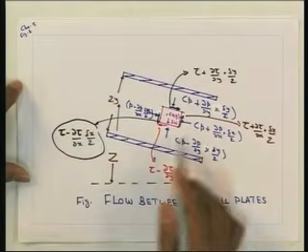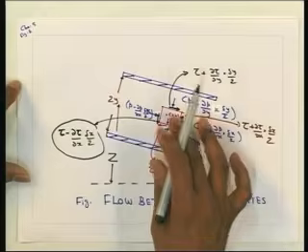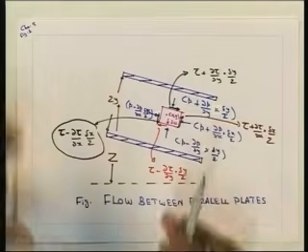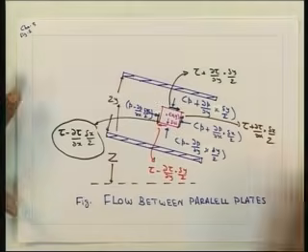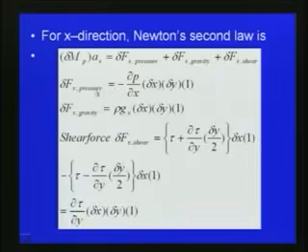So, now we are considering this control volume and a fluid element, with all the pressure force and shear force. Finally, we can write with respect to this the delta fx pressure as del p by del x into delta x into delta y, and if we consider the unit thickness it is multiplied by 1. Similarly, the gravity force acting on the fluid element is delta fx equal to rho gx into delta x into delta y into 1. So, this gives the gravity force.